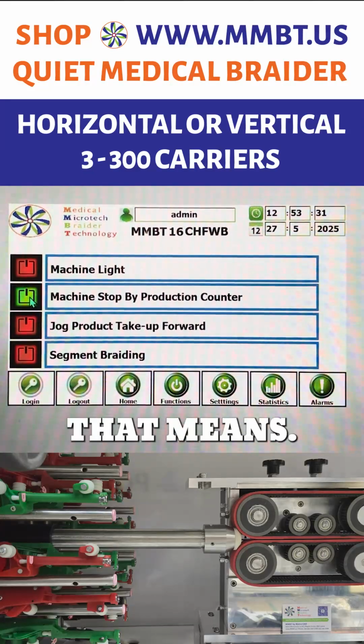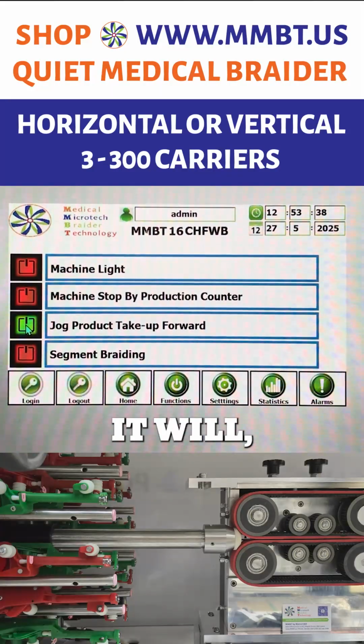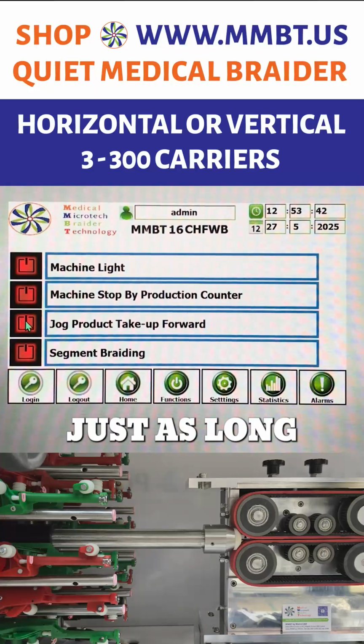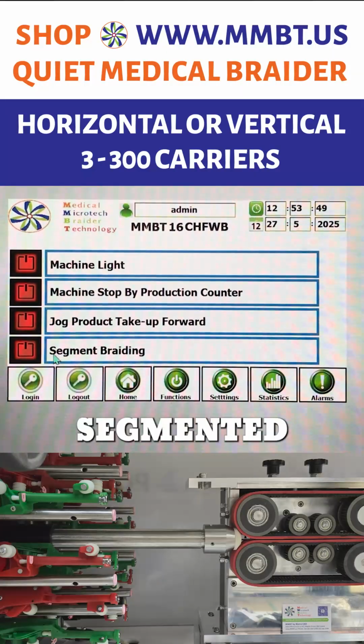That's what that means. Jog product take up forward. While holding and pressing this button, it will turn the take up motor just as long as that button's held down. And this is where you can enable or disable segmented braiding.